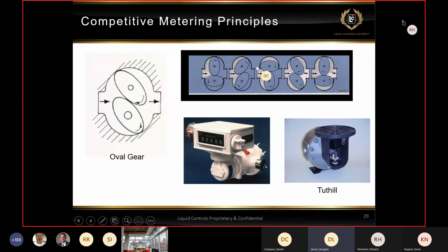So if it's a light product, normal gear teeth that are cut into it work well. But if it's any viscous liquid, now they have to know the viscosity of the product and it can't change very well, because then they actually remove some of those cuttings of the gear teeth on the oval gear to make the product come out to the other side. Otherwise, their pressure drop is extremely high also.